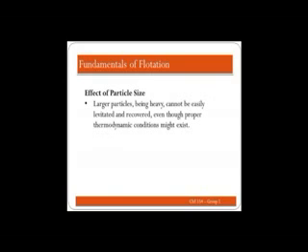Last is the effect of particle size. This is the most significant variable of flotation separation. Larger particles, being heavy, cannot be easily levitated and recovered, even though proper thermodynamic conditions might exist.